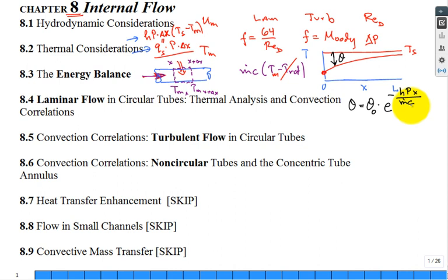All right, we already talked about what is M dot, we already talked about what is C. I think you know what H is. But what's P in that equation? Perimeter, not pressure, right, just perimeter. The T, like the TS, a little X right here. Yeah, like a time, but it's a location X. Then X goes from 0 to L.